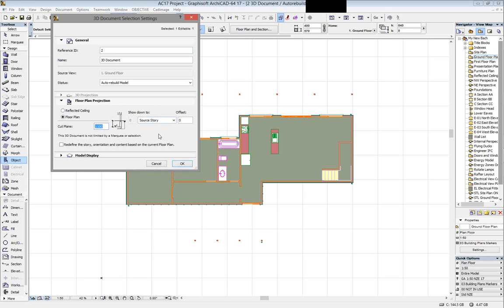Another really good one that we came up with was the ability to show mid-floor framing and the supporting walls beneath. This has always been a relatively complicated scenario. We had extra layers, or you could draw lines, or you could do all sorts of weird and wonderful things. But simply, come into a 3D document, set your cutting plane to somewhere within your modeled floor joist, because of course, we should all be modeling our joists, I suppose, and then set it to look down so that it sees the tops of the walls beneath.